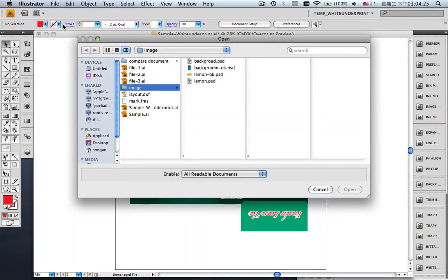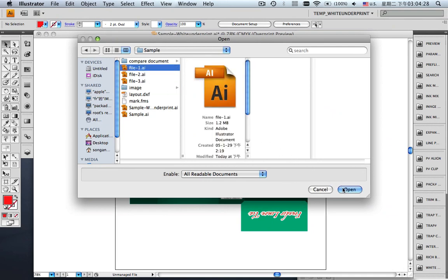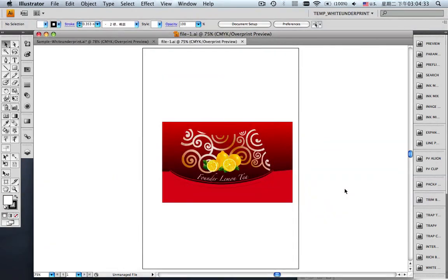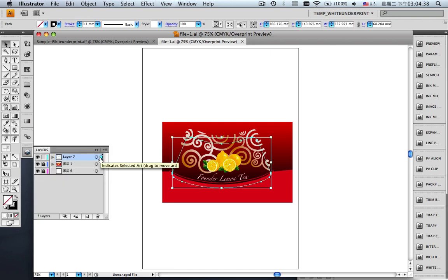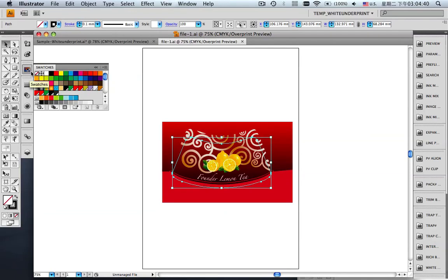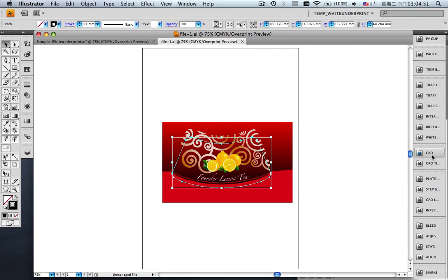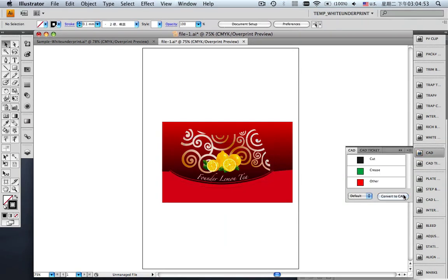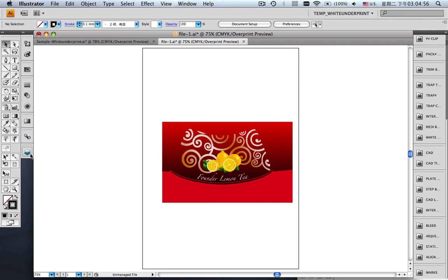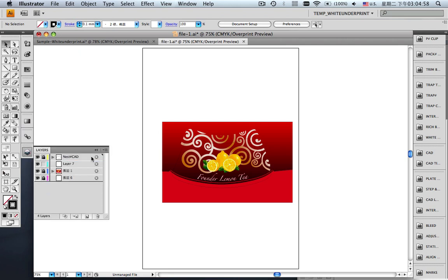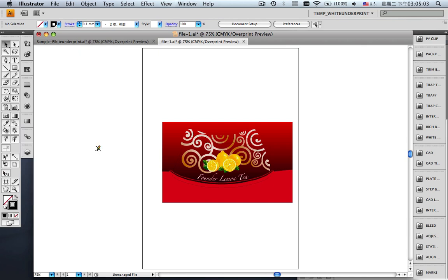After trapping, ink conversion, and other important prepress processes, the package design can continue to be step and repeated in the press layout. First, we open the package CAD file, which needs the step and repeat. We set the box structure to the current CAD file, and after setting, we need to click the Convert to CAD button from the CAD panel, and then we can convert the CAD file to the special NetSharp CAD structural lines.